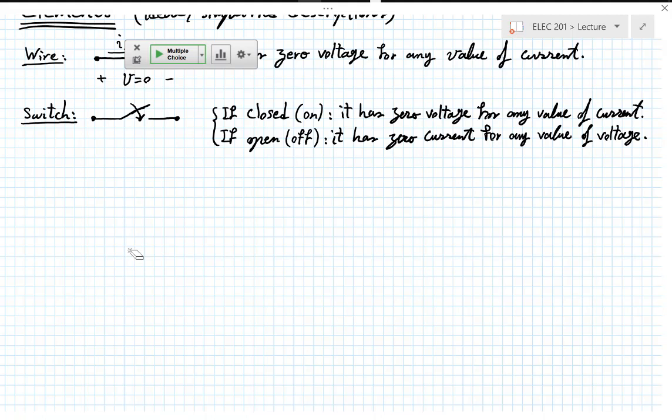So a question here is, there's maybe something about this that makes us uncomfortable. Can we say a little more than it can be anything? The answer is no. The two sides are completely disconnected. It could perfectly work out that the rest of the circuit is such that the voltage difference between the two ends up being 0 by accident, just because of the rest of the circuit. So we don't know that it's not 0. 0 is just one value like any other among infinite possibilities.